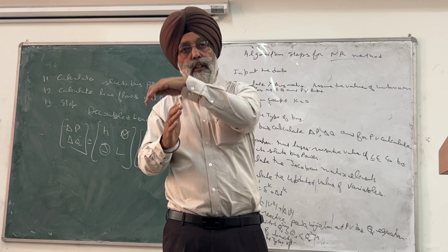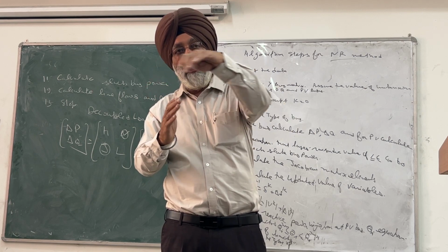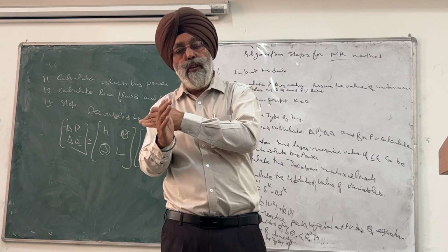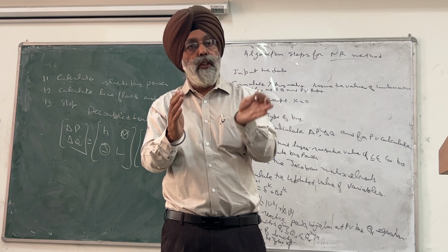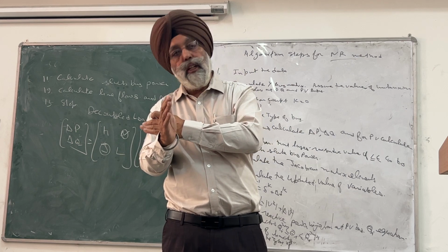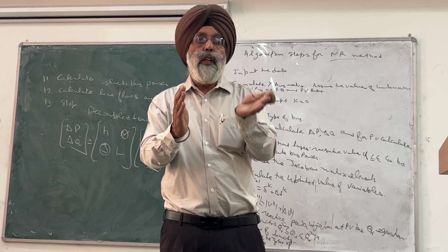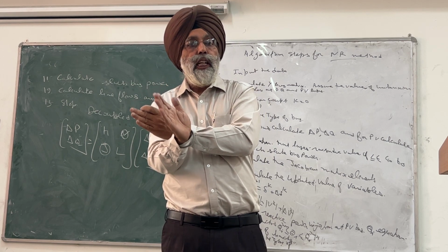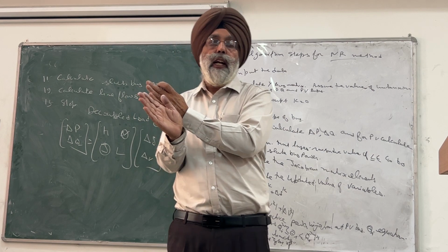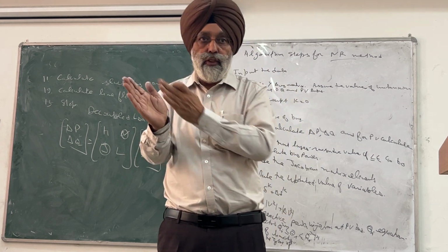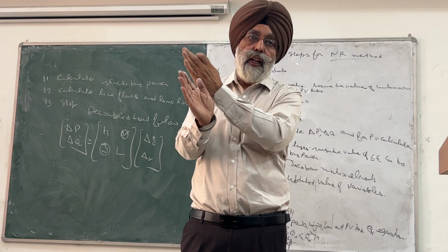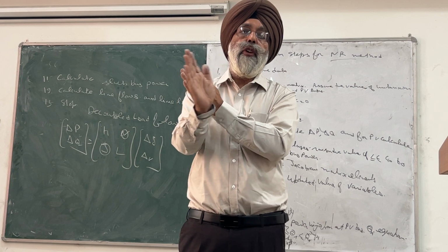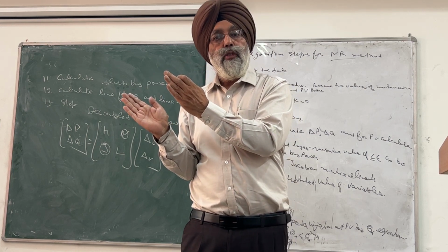So that will affect the synchronous rotor field. The rotor is rotating, the rotor is a field. Also we have the synchronous field induced in the stator. So our field is always rotating at the synchronous speed. We have the synchronously rotating field. But our rotor can change its position. It is not lying with the synchronous axis. It can be ahead of the synchronous axis or behind the synchronous axis.